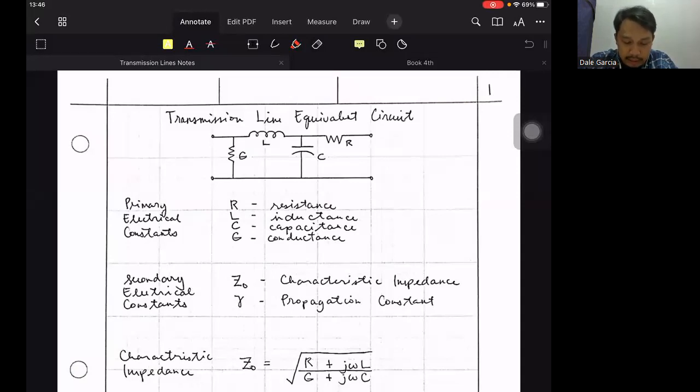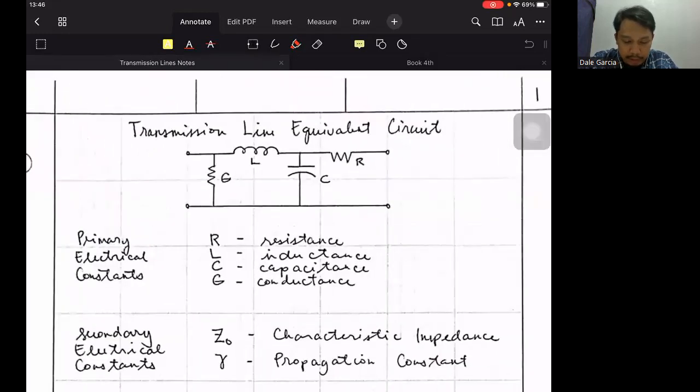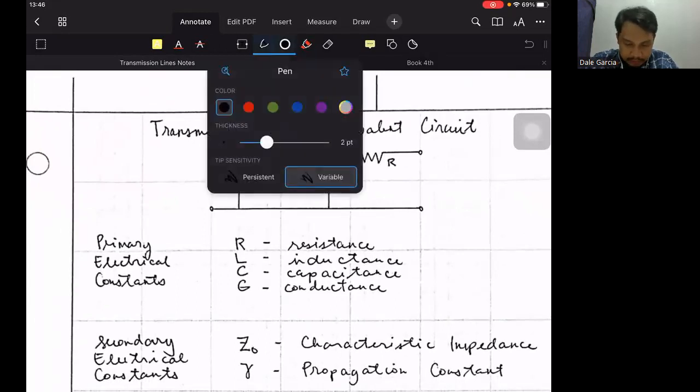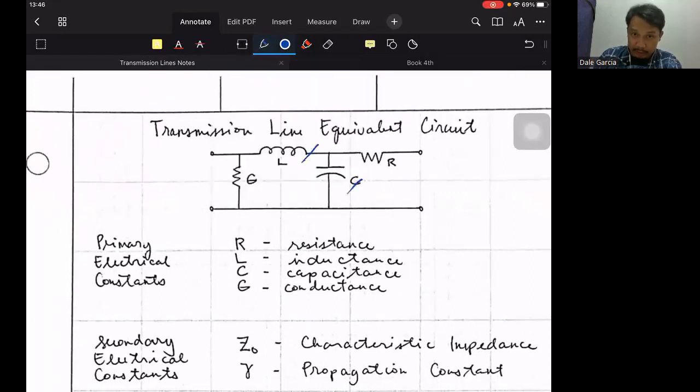So for substantially higher frequencies, there is an equivalent circuit for this transmission line. It is no longer a plain set of conductors only, but it exhibits parameters: not only resistance, but also inductance, capacitance, and conductance, G, in between the lines. So we could use this as our equivalent circuit of a pair of transmission lines at